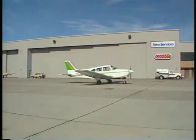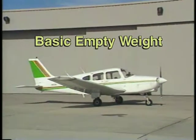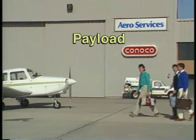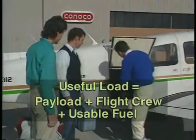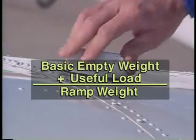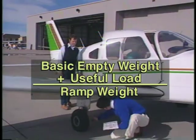The starting point for any calculation is the basic empty weight, which includes the airplane, optional equipment, unusable fuel, and full operating fluids, including oil. Payload includes the weight of the passengers and any cargo or baggage. Useful load includes the payload and the weight of the flight crew and usable fuel. The sum of the basic empty weight and the useful load is called the ramp weight, which is the weight of the aircraft during ground operations.